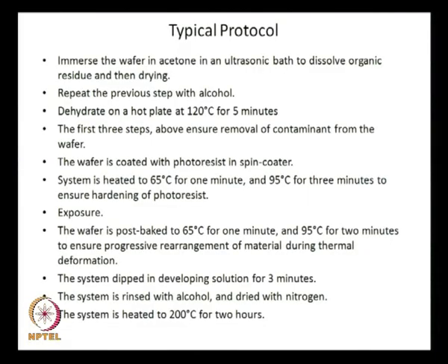So, a typical protocol would be: immerse the wafer in acetone in an ultrasonic bath to dissolve organic residue and then dry it. Take the silicon wafer, 500 micrometer thick and 4 inch in diameter, and immerse it in acetone in an ultrasonic bath.